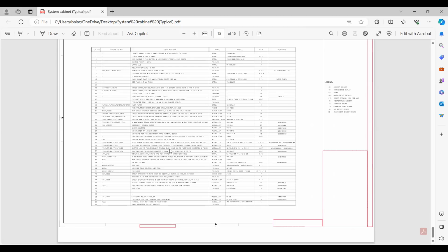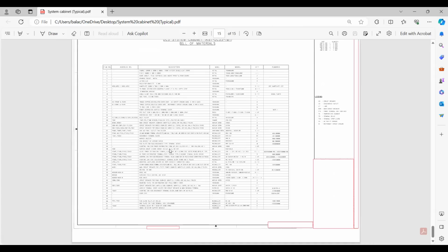So just as a recap, what we have talked about actually, this is about the system cabinet drawing, right? Yes, system cabinet. As part of that, the first item was external layout. Okay, then channel based details. Then third, internal arrangement. Fourth, sectional view. Bit of complex, but of course the system designer, CAD designer, knows easily. Then the power distribution, 120 volt AC. Then the power distribution for the front nodes and the power distribution for the utility, and drawing for the alarm. And yeah, then earthing, then the nameplate.